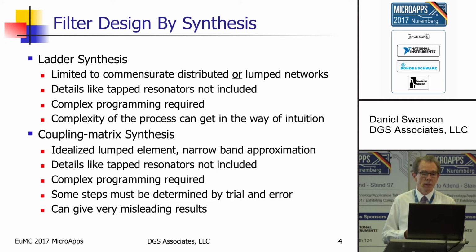And we can get a good basic circuit, but there's a lot of details that we can't synthesize directly. Like if you're doing a Combline or an interdigital filter and you want tapped resonators at the input and the output, you have to add those later, usually by optimization, because they can't be directly synthesized. It's not commensurate with the rest of the network. Other details like the tuning screws also have to be inserted, usually by optimization. So there's some complex programming required.